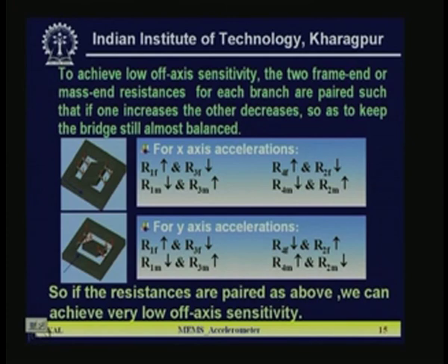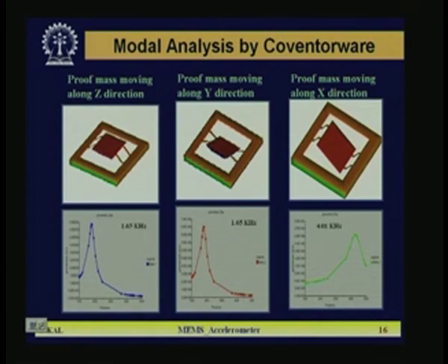Now this is okay. The next point is I have to go for designing so that the natural frequency should be greater than 100 hertz. For that we have to do some modal analysis, because any structure, if you do the modal analysis, will go for the first mode, second mode, third mode, like that.